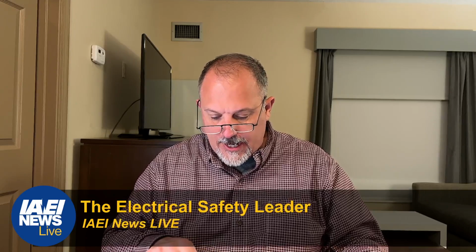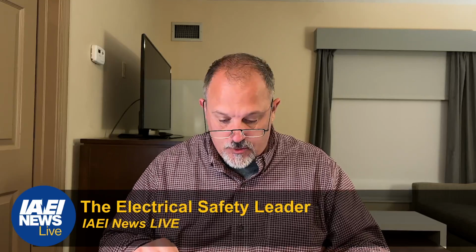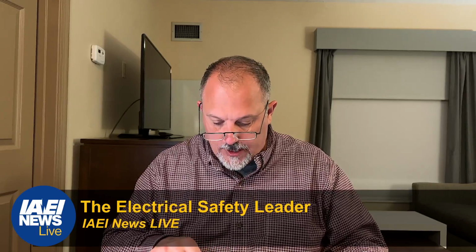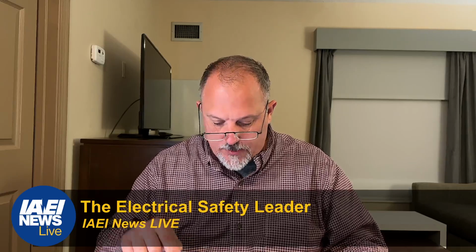Indoor equipment requiring dedicated equipment spaces. Where equipment other than service equipment requires dedicated equipment space as specified in 110.26E, I'm reading in 210.63B2. The required receptacle outlet shall be located within the same room or area as the electrical equipment and shall not be connected to the load side of the equipment's disconnecting means. So we try to add some clarity. Here's the problem with that one.